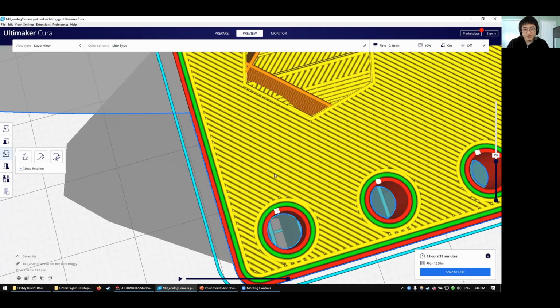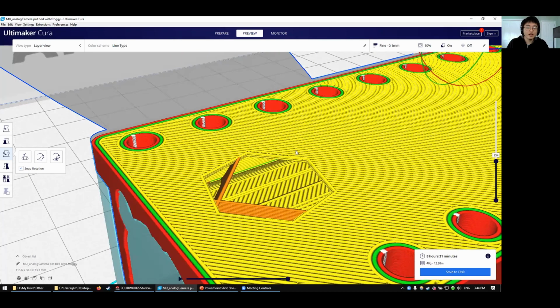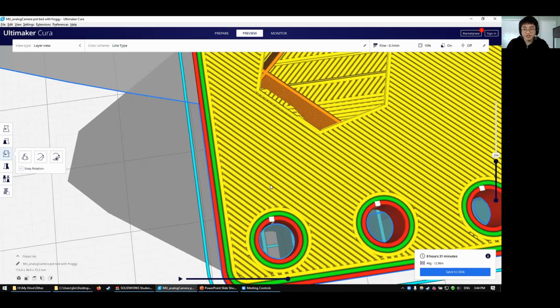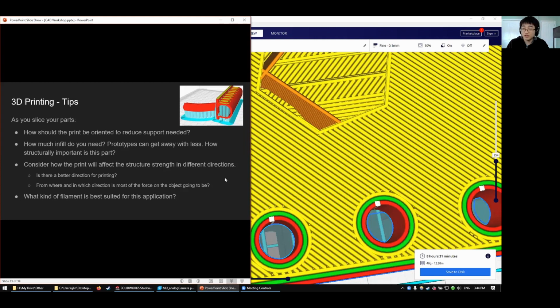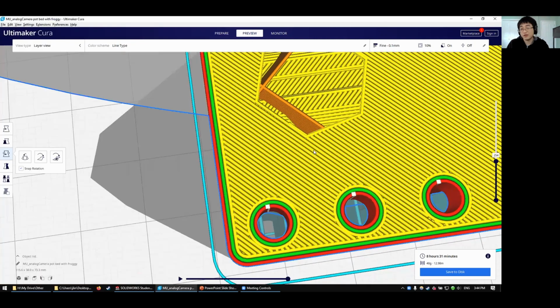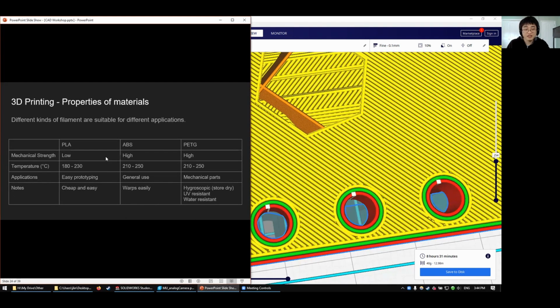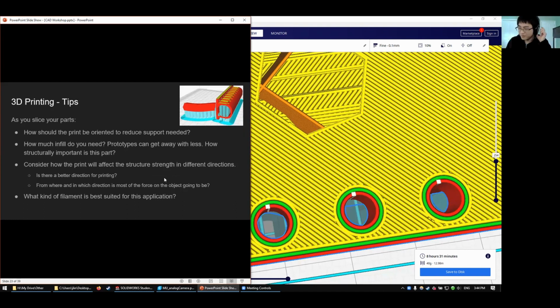It's not super important for this one because this one just holds a camera. It's just mounted somewhere. But if we're going to be printing stuff that's structural or that's going to be supporting lots of heavy stuff, then you will want to consider what direction the printer is printing it. And if so, how you can game the system is by rotating stuff. Or if you want to get super advanced, you can see if there are some other options, or maybe even edit the G code manually to modify the print directions. Well, that's tough, but it's important to consider as you print structural components.